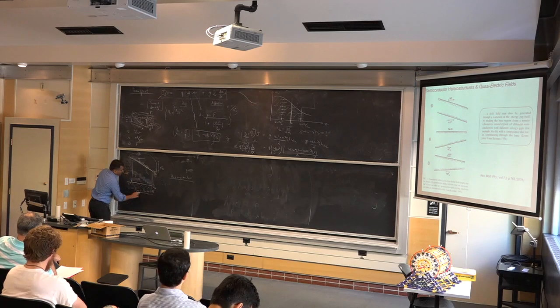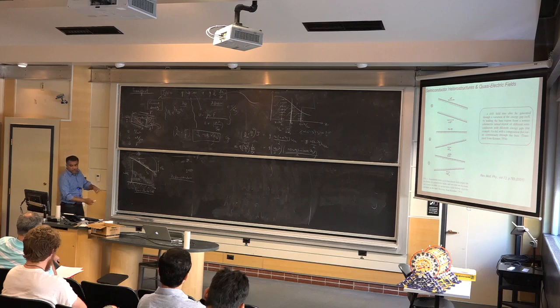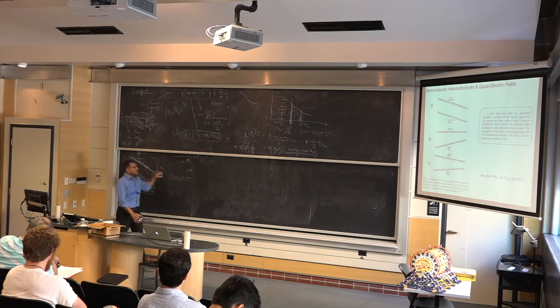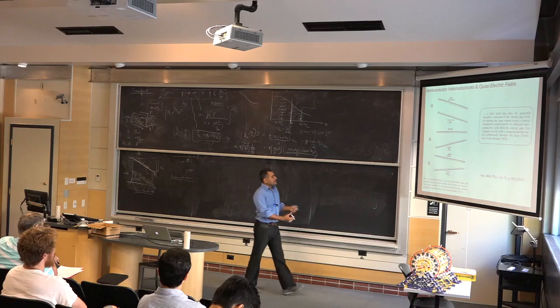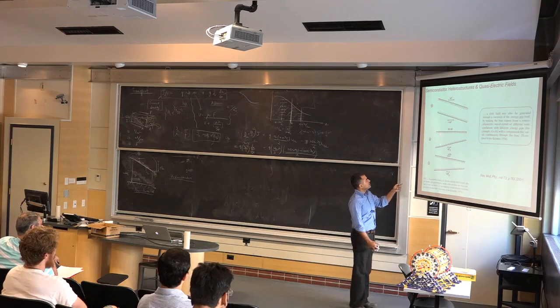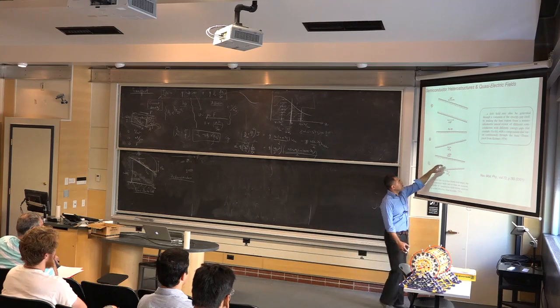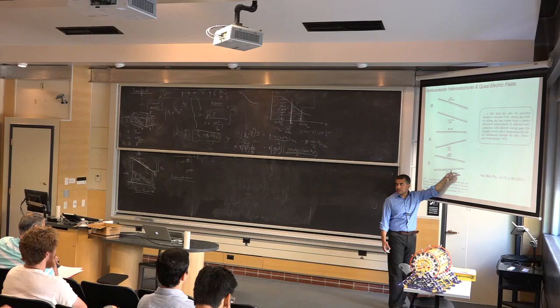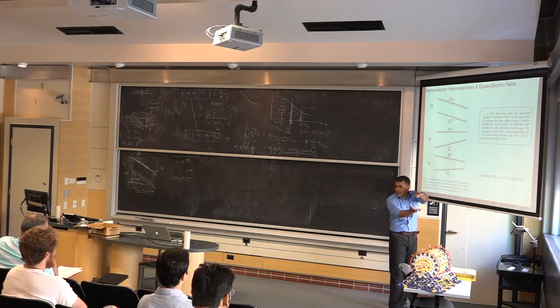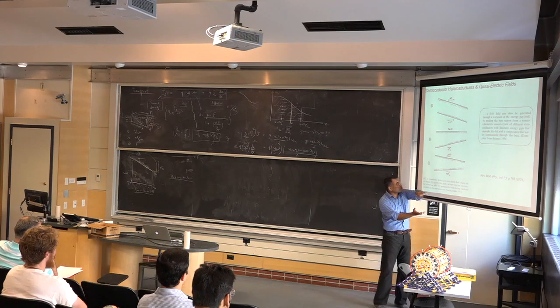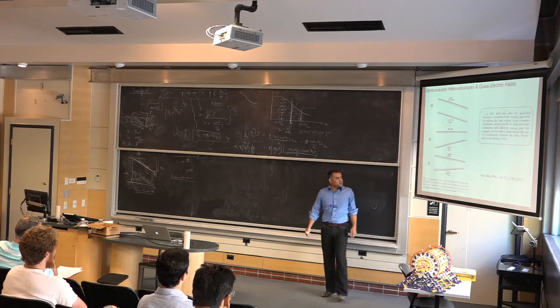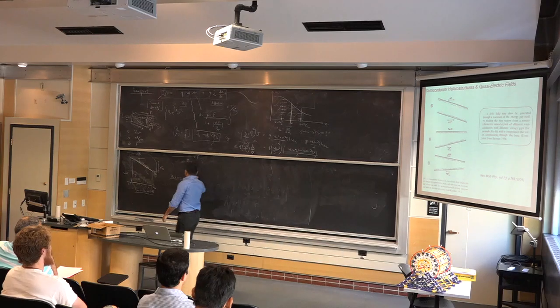but it's saying that by careful choice of materials, you can create these built-in fields which are not because of an external battery, an external voltage. Right? And then clearly you can see that for that you need band gaps that are changing in space. You can create a situation like this where both electrons and holes are moving to the right, because the holes want to be on the top of the valence band, electrons want to be at the bottom of the conduction band. They're both moving to the right. Clearly this situation is somewhat counterintuitive, but this is what semiconductor heterostructures do.